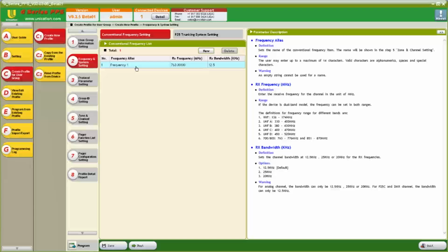And then by the time we get to the end, we're ready to program the pager. So what we'll do is we will put in a page channel. We'll just label it page. And we can put in whatever frequency we want. And we'll want to set whether it's wideband or narrowband. Everything around here is narrowband right now, so we'll leave that alone.